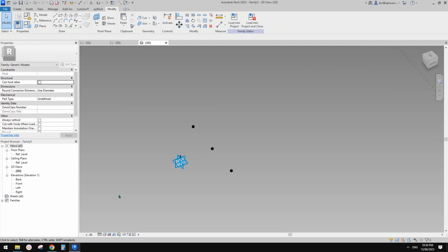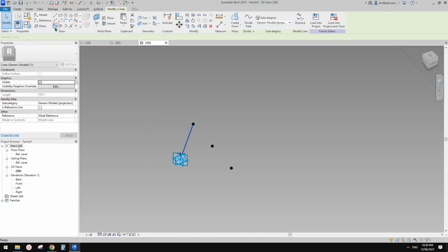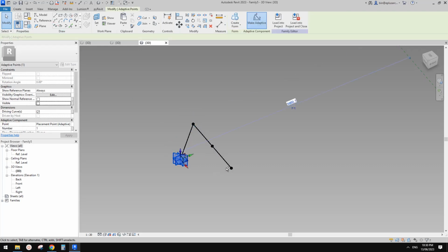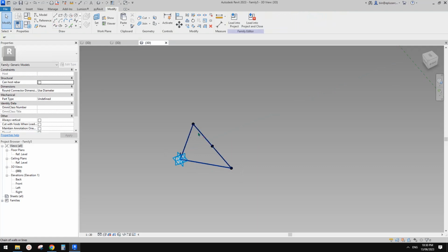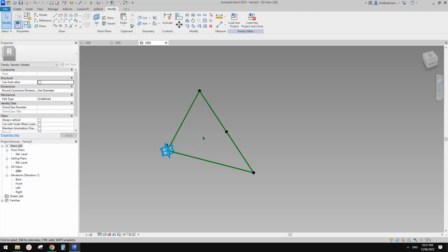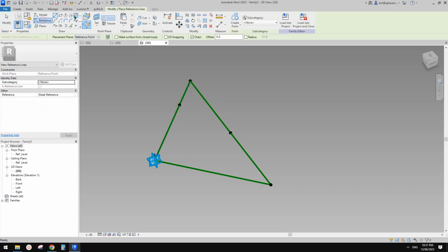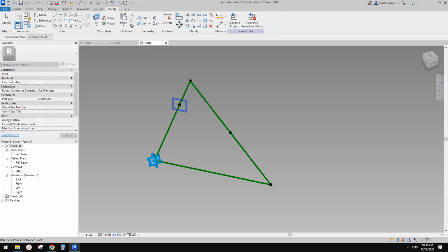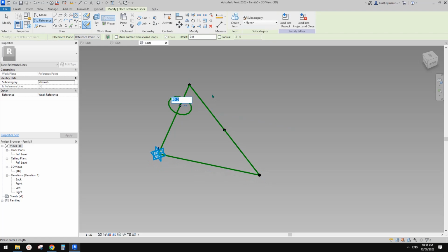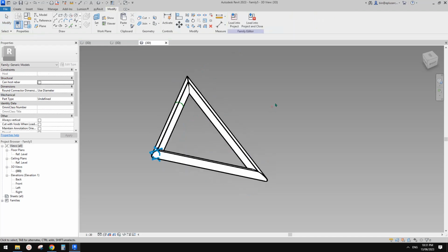Then we can connect these points. Use draw spline through points, and another one, and another one. Once we have this model line, we can turn them into reference lines, and then we can create these. We can just place a point, draw on face, place onto the reference line, reference circle, draw on work plane, set work plane, pick this one. I'll place it maybe 30, something like that. Now we can select the profile and also the path and create a form.